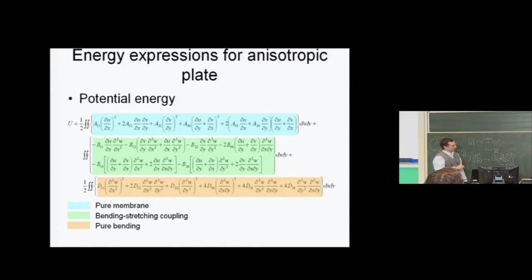So while the top line only involves the in-plane displacements U and V, and the bottom line here involves the W displacement, in the middle we have them combined. And you can see how that really complicates things and why it's very advantageous from a mathematical algebraic perspective to actually have a B matrix equal 0. That's the general expression if it's in terms of displacement.